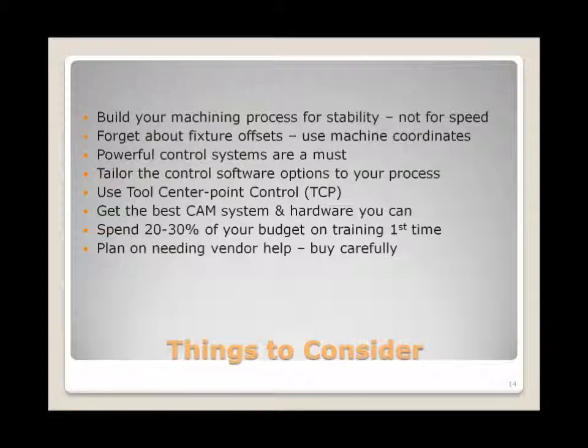One of the downsides to vertical machining centers is they have a door on them. Now, obviously, you need a door to feed these things, but most often the door is used to get in and rescue the process, either chip control or point coolant or what have you. In 5-axis machining, we want to build a machining process that does not have to be rescued by the operator frequently.